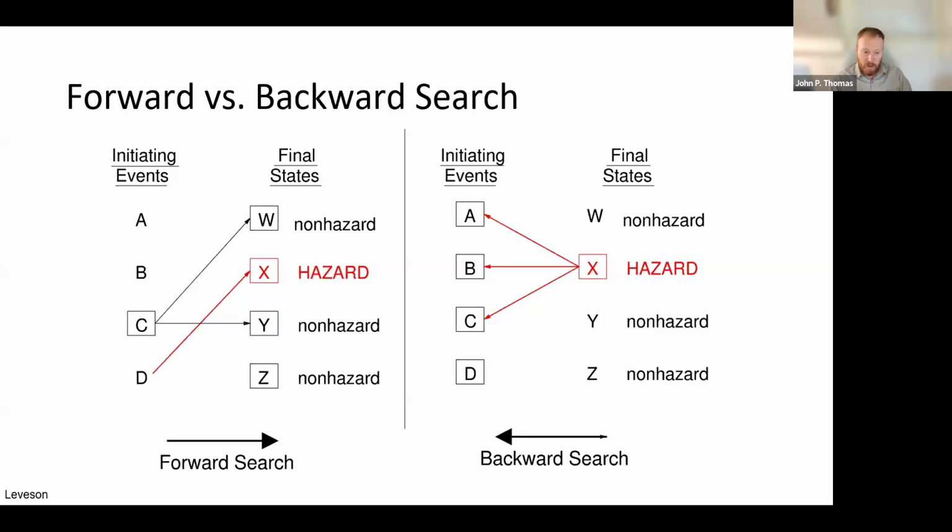You can do the same thing in reverse with a backward search. Some folks view FMEA as a backward search, starting maybe with a failure mode or maybe a failure effect. In aviation, there are 5 effects that are defined for the industry, and sort of working backwards. What are the causes and the mechanisms that lead to those failure modes and effects? That would be a backward search. So your guiding principle as you develop a scenario is just go backward in time, right? So the time is sort of the variable that we move forward or backward through in this scheme.